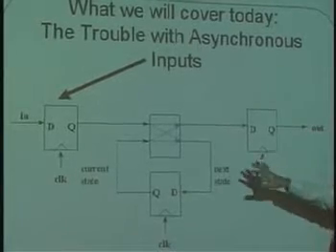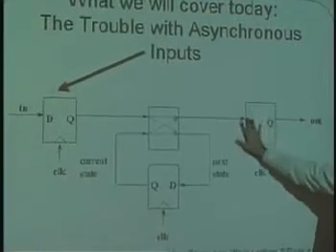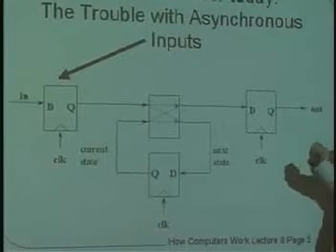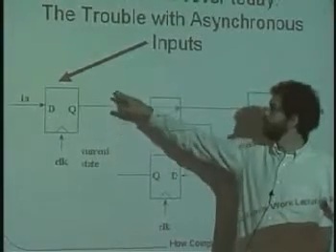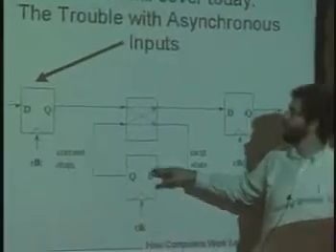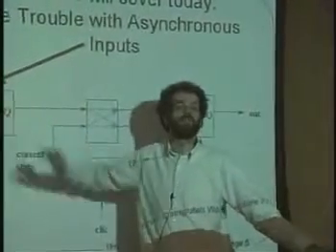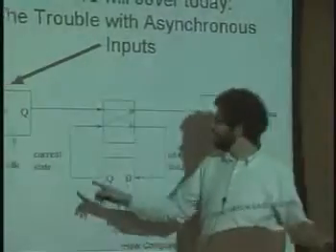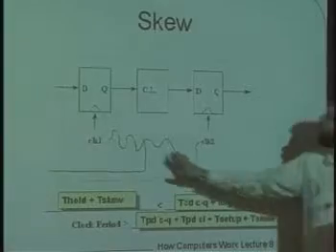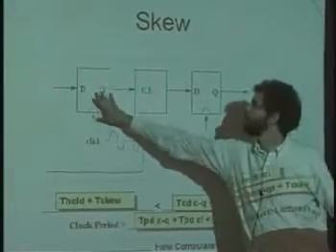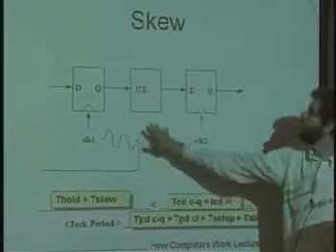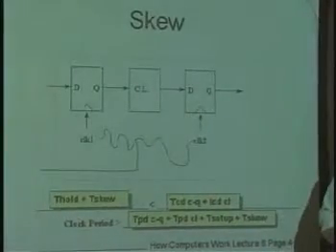Well, we talked before about adding flip-flops to the output of the system to get rid of glitches and to get rid of hazards on the output. It turns out that one of the ways that you fix problems with an input here causing a change here during the setup and hold time is you put another register on the input. And here's the idea. I know from the previous diagram, the unwrapped loop, that if I set up a chain of a register and combinational logic and another register, that I can go ahead and clock these all at the same time and I'll obey the timing constraints.